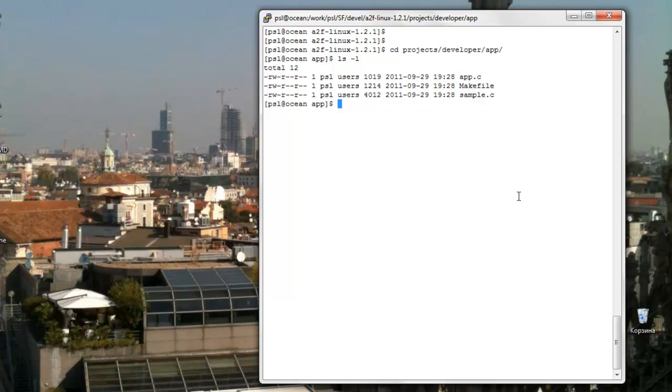These source files are intended as a starting point for development of new user space applications and device drivers. The development of new code is to create a clone of the Developer project. In the Linux SmartFusion development environment, there is a make goal that allows us to do exactly that. Here is how a new clone of the Developer project is created. I'm going to call the new project Test1.